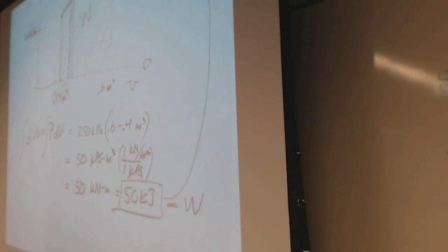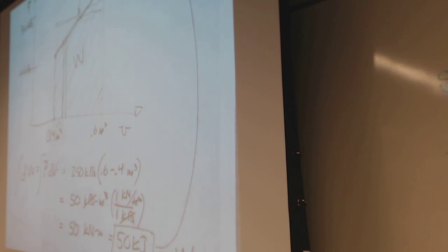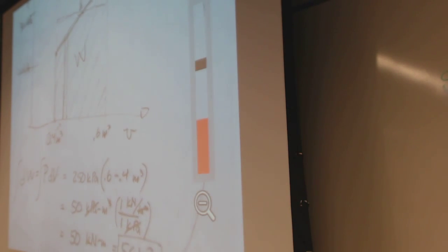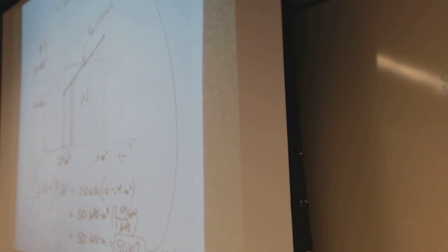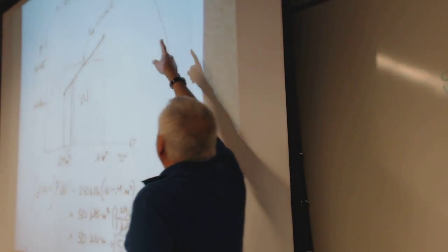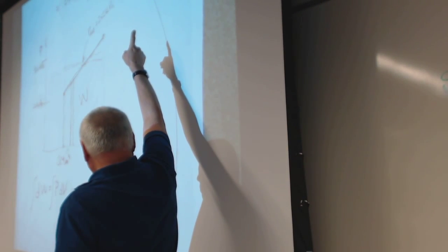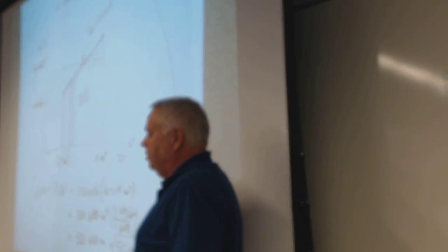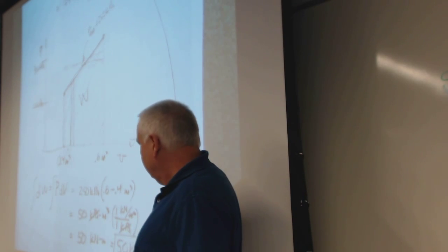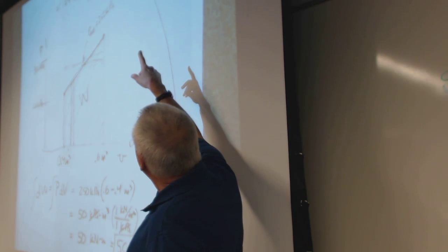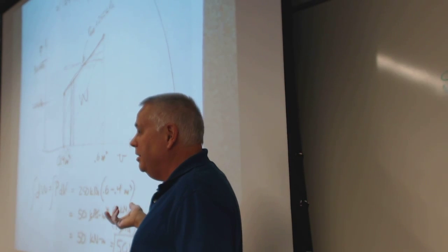Our other number was the total amount of energy. Not only did the work get done, but the pressure was raised and the temperature was raised. And so out of all that, what we could say is that that's the change in enthalpy total. This was the change in the work that was done total. So 50 of the 460 was work, and 410.75 was probably internal energy.